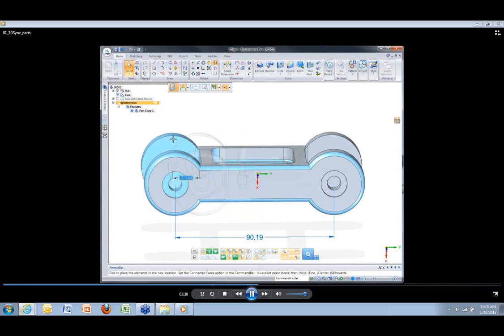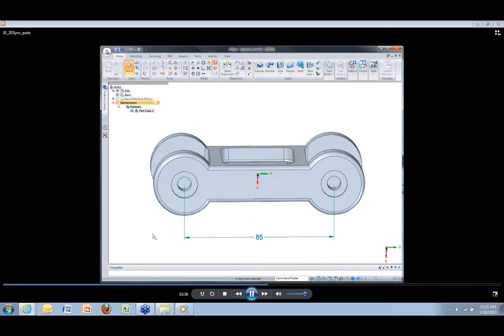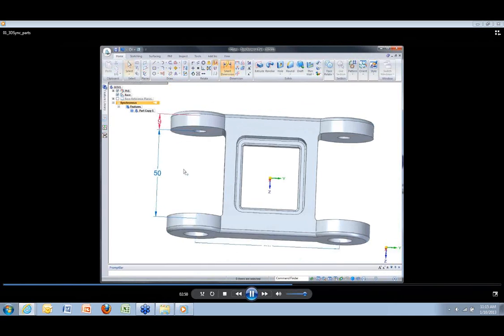Let's make some dimensional edits to this SolidWorks part. Unique to 3DSync are 3D driving dimensions which can be applied between key geometric features. When added between the alignment holes, we can edit the spacing directly. 3D driving dimensions can be placed in a stacked configuration and locked to preserve distances. As the interior clearance is modified, notice how the linkage thickness remains.